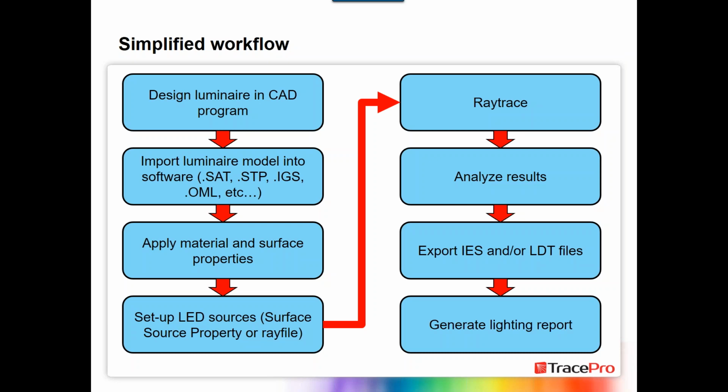You'd analyze the results. From those results, if necessary, you could export an IES or an LDT file. Basically a photometric file that can also be used by other programs, such as Dialux, Lightstar 4D, AGI32, programs like that. And then as a last step, you could also generate a lighting report that you could pass on to your customers or your vendors.